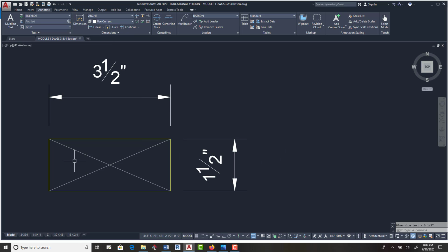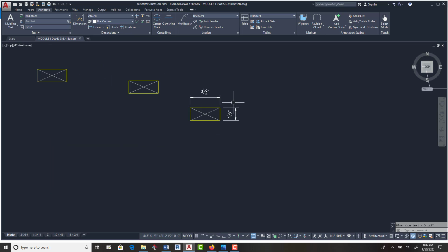This is called a 2x4, but it is actually 1.5 inches by 3.5 inches because it's been planed down to make it smooth. You have to draw an actual 1.5 by 3.5. You can't draw it 2x4. You can't draw it 2x6. You have to draw the actual size. Because if you stack up a bunch of these and you've drawn them at 2, if you stack up 10, you're going to be 1/2 inch off by the time you get to the roof. And so you don't want to ever do that. You want to draw everything as its actual size.